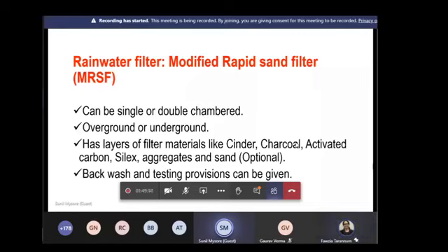Yes, please. Essentially, you have to have a settling tank where there are dusty conditions. For example, if your house or your factory is next to a graphite factory, or a factory where there's a lot of soot coming out, there you need a good settling tank. A rule of thumb is 1 liter per square meter as the volume of a settling tank. But if you are coming from a very dusty area or near any factory area where there is a lot of soot coming out, you can increase that volume.